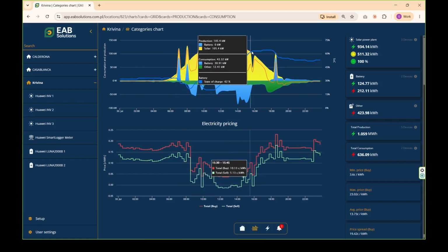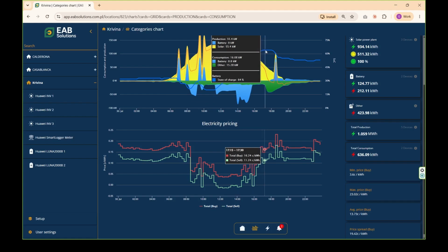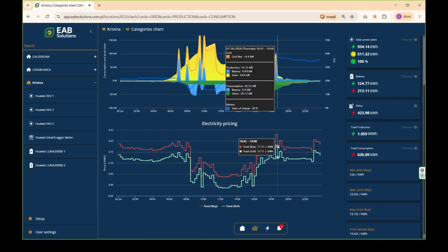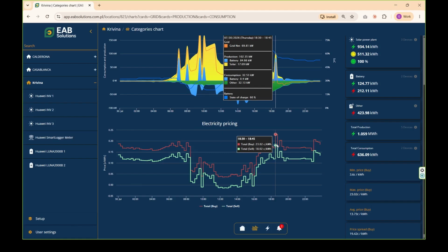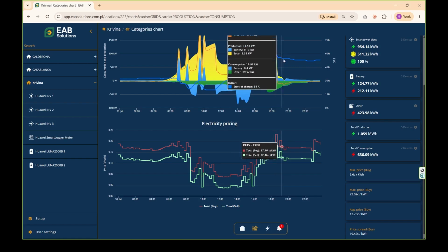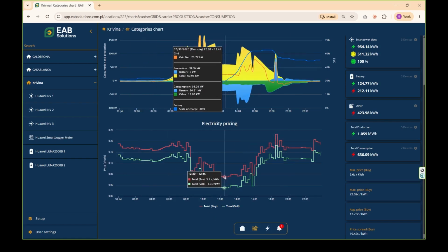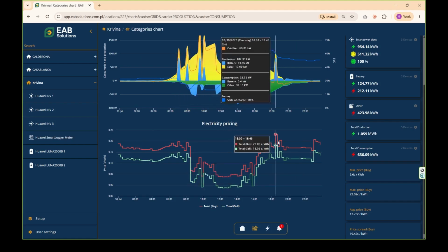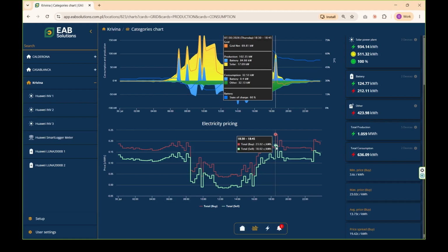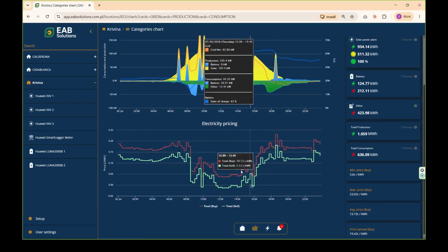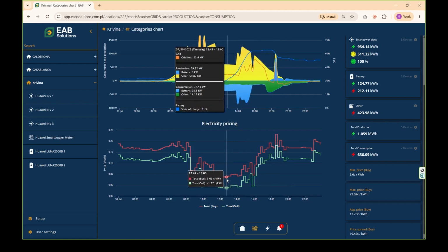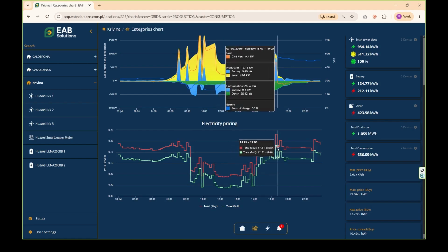And once the battery is charged, here you see we're full. We wait. The battery is flat. We wait for the moment of highest price, which is this one here, 18 cents, to discharge the battery. That's the moment when we discharge all the energy we stored. And that way, we're monetizing energy that was charged here at this price, at 3.7 cents, which is what we bought it for in this area, to resell it at 18 cents, and that's how we do price arbitrage. Buying at 3 cents and selling at 18, the difference is 15 cents.